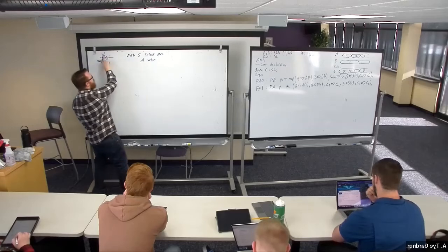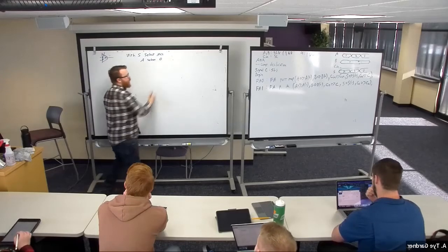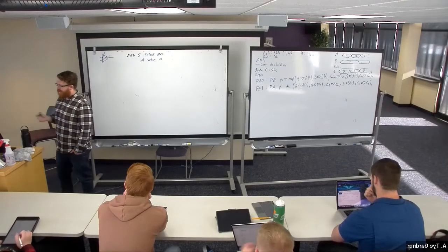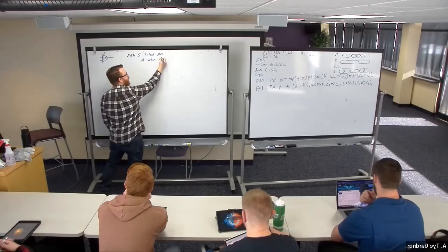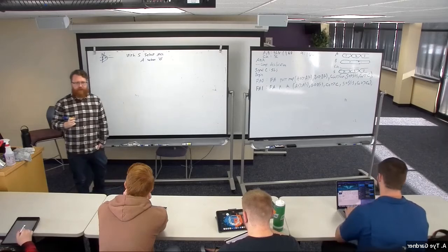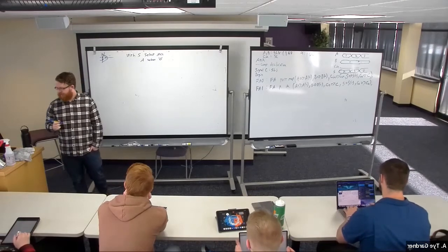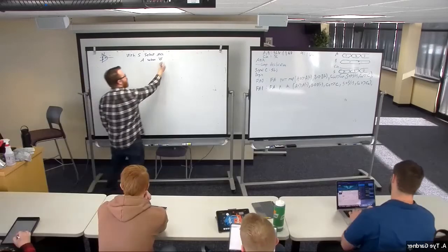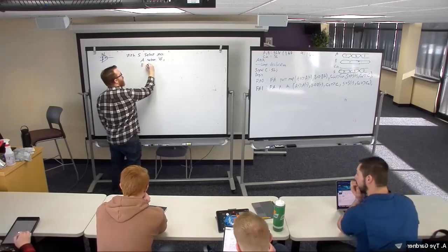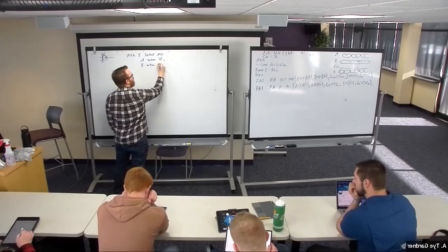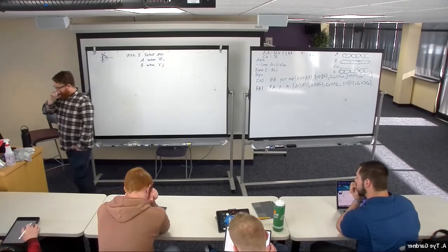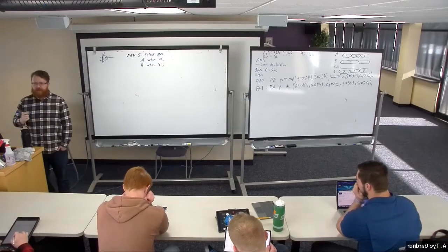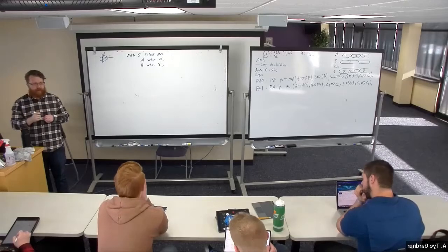Well, S needs to be 0. And in this case, 0 is actually a bit, so we have little apostrophes. Then we say comma, B when 1. Done. I built a mux.